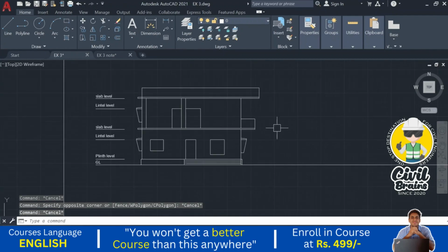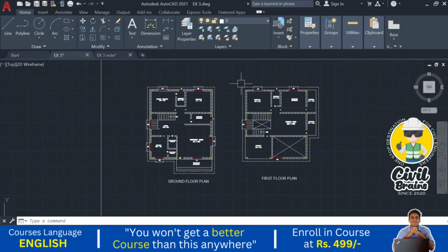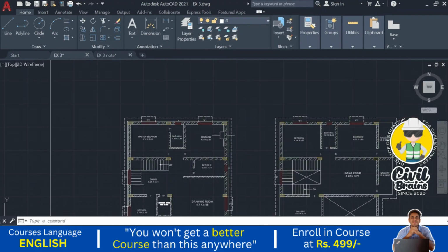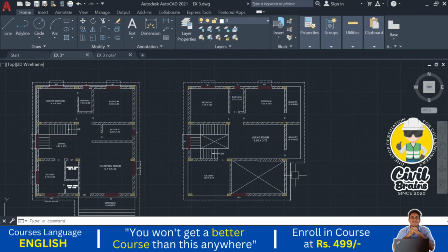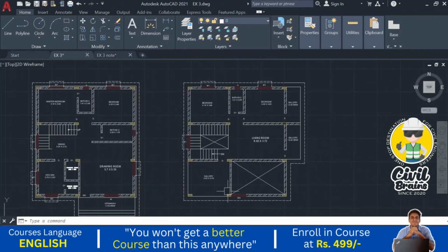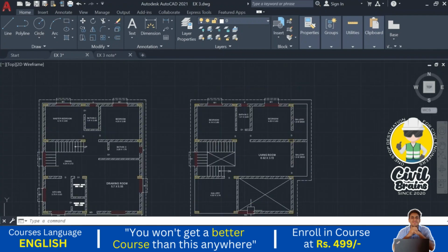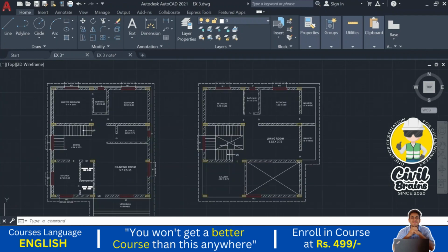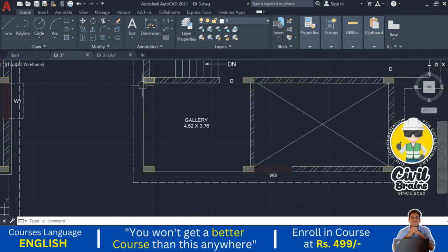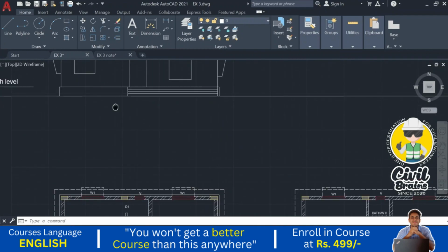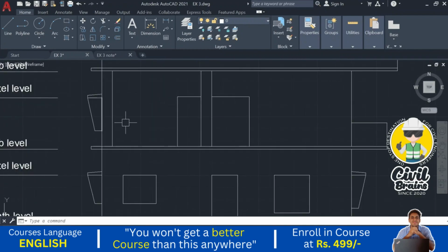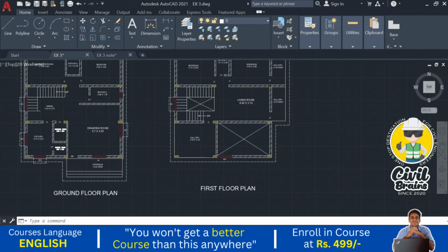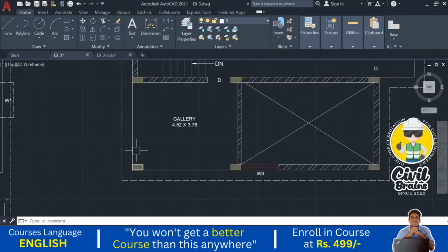Okay, so now here is our front elevation. You can see that in the ground floor everything we have covered, and in the first floor also we covered all the things: slab projection, gallery, railings, windows, doors, everything. Observe one thing: in the gallery we are providing railings, so we need to show the railings here. In the first floor, from column to column we are providing the railings, from this column to this column, and from this column to this column.